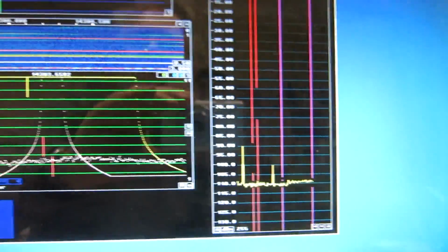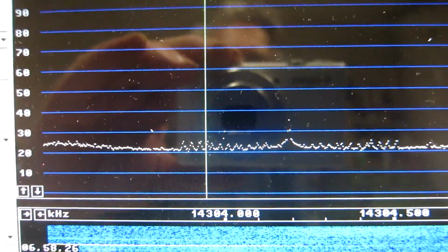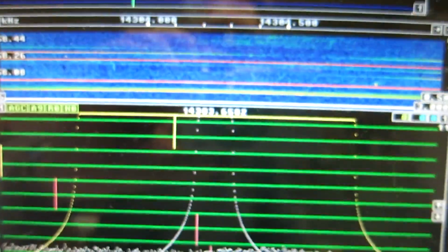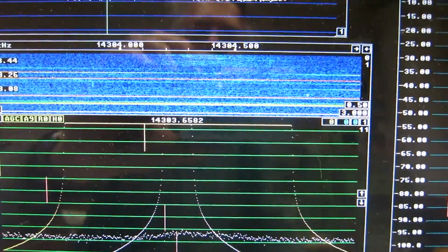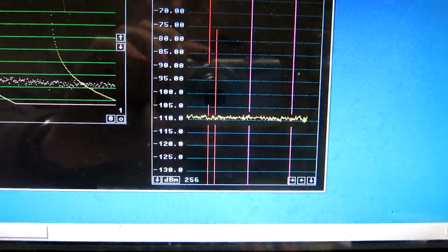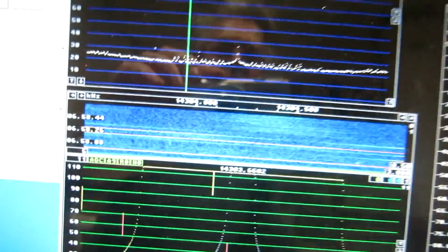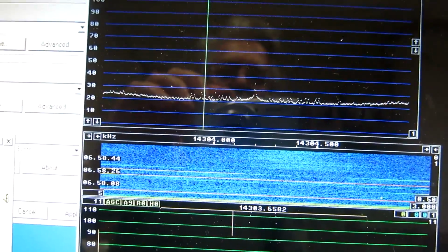This is some kind of noise spur. You can see we have a lot of nasty things, and you can see in the waterfall something of that comes within the 1 kilohertz, but it doesn't contribute more than about 2 dB, so I ignore it and step again 5 kilohertz.